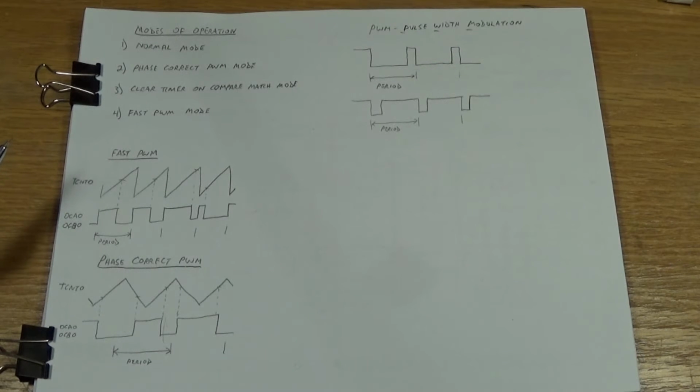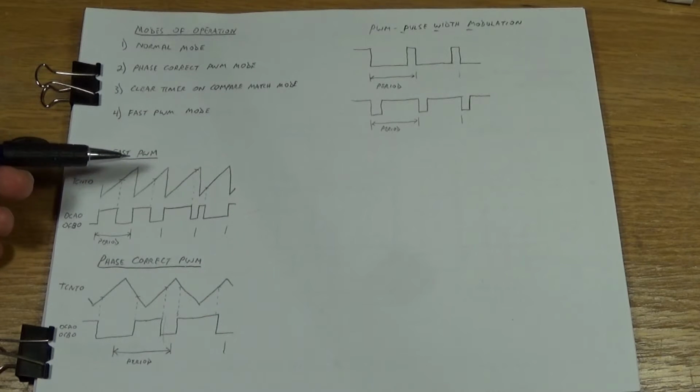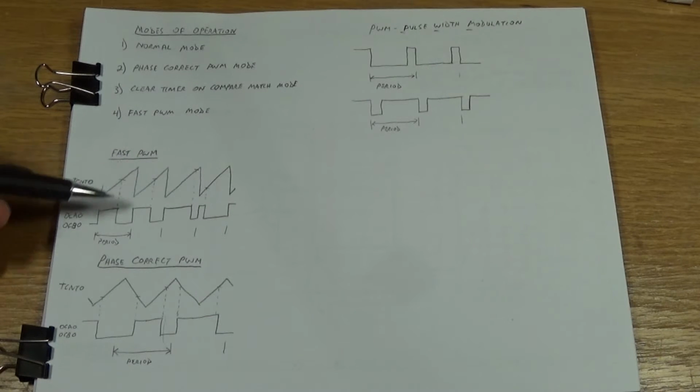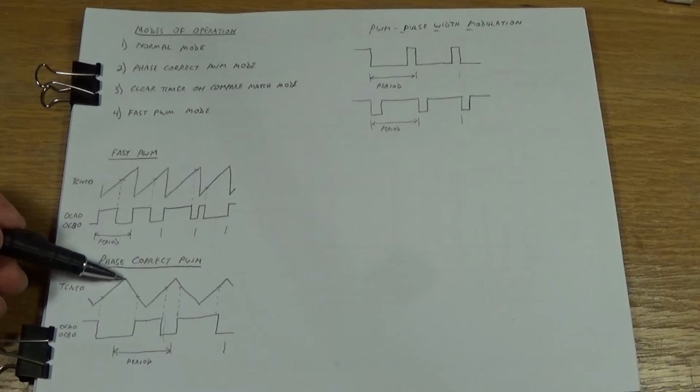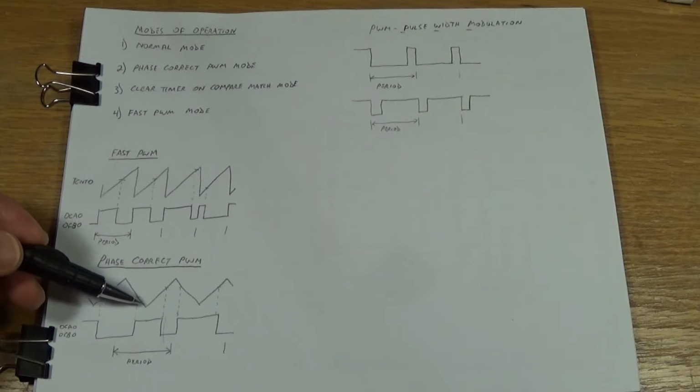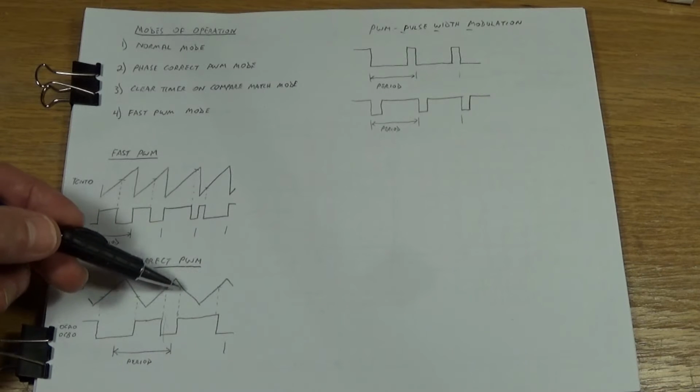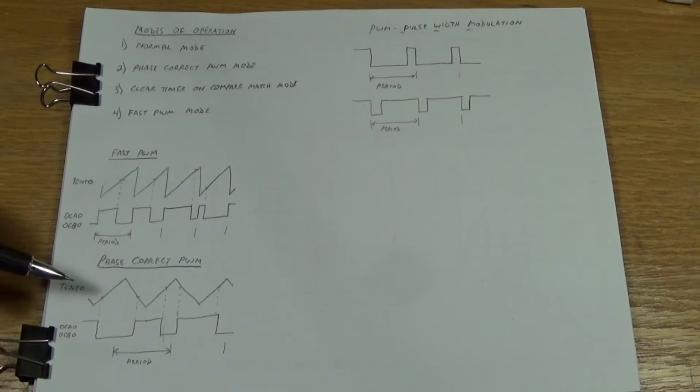In this case, the timer counter register will increment from 0 till it reaches the maximum. In the manual, when you read this, you will read the term top, and that's the maximum count that the timer counter register reaches. So in this case, the timer counter will increment to top, which in this case is 255, or the maximum count of 8 bits, and then it turns around and starts to count down to 0, and then it increments back up and down. So you get this more sawtooth wave.